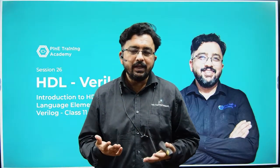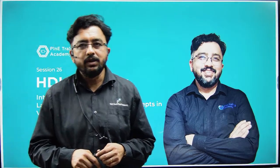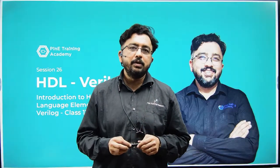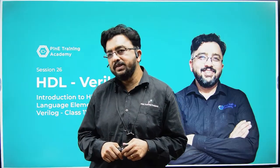So what exactly happens if we initialize an array, or design an array? If I'm talking about FPGA, then this will implement a memory. If you implement this on ASIC, then this will give you some register bank. This register bank or memory plays a very important role because FPGA is not a non-volatile device.